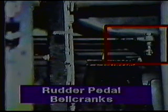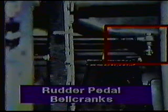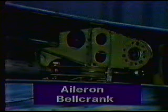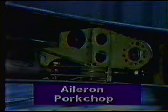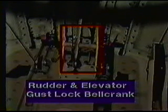The two units mounted on the forward pressure bulkhead that link the pilot's and co-pilot's rudder pedals are called the rudder pedal bell cranks. The unit located in the wing near the inboard end of each aileron is the aileron bell crank, sometimes referred to as the Porkchop because of its shape. The unit mounted on the forward side of the forward canted bulkhead that actuates the rudder and elevator gust locks is called the rudder gust lock bell crank, or rudder and elevator gust lock bell crank.